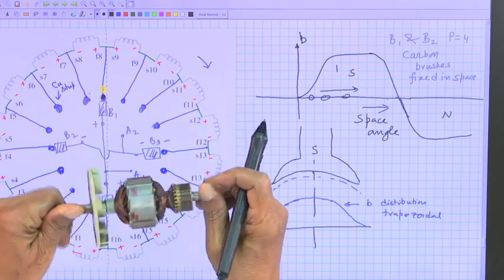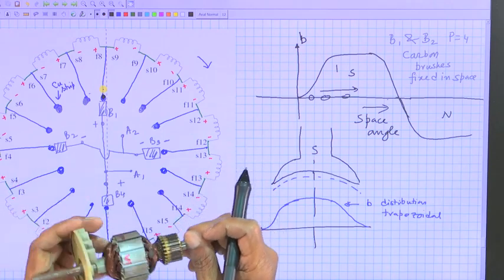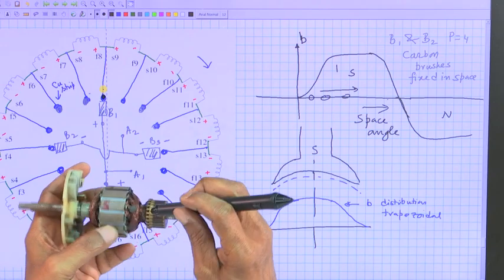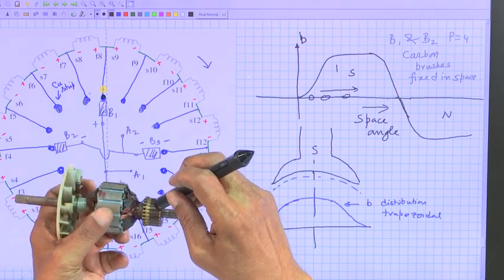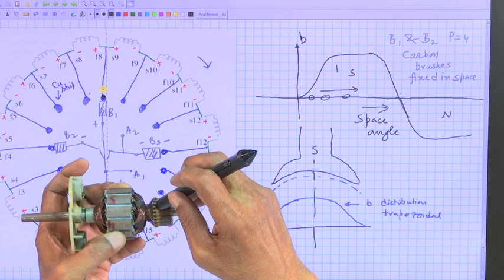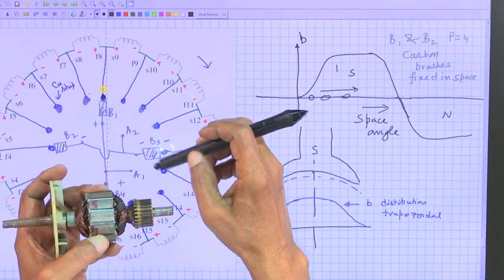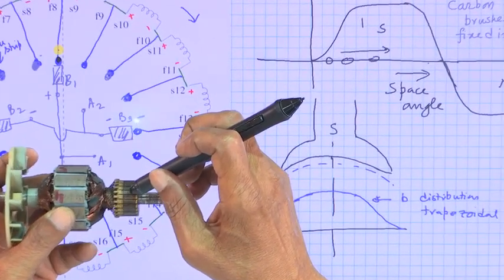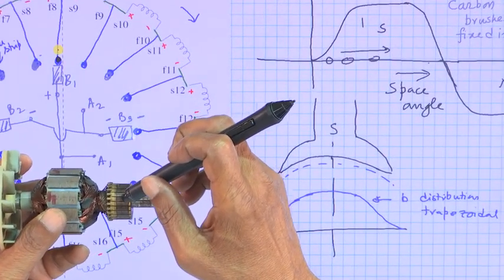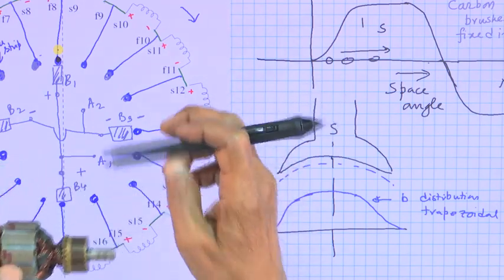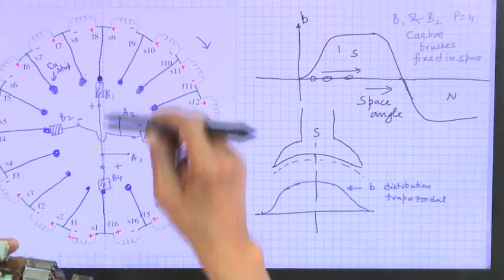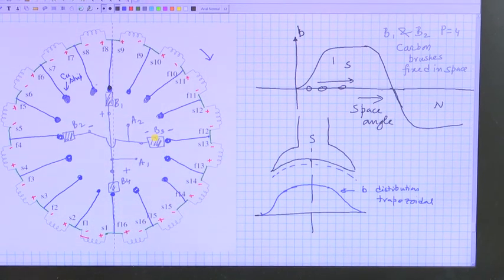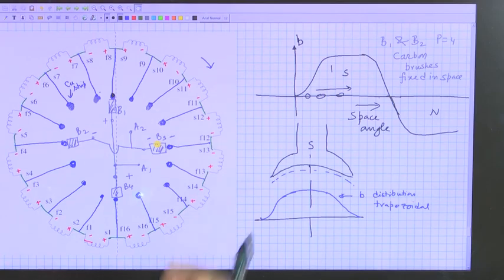So, this whole thing will rotate. Okay. And then we will have carbon brushes. Suppose this tip is a carbon brush placed in space like this and fixed. Therefore, as it rotates, this brush does not rotate, and it will touch whichever coil comes in that position, connecting that particular commutator segment, ensuring that B1 and B4 will always remain positive, B3 and B2 will always remain negative in polarity of the voltage, thereby giving you a DC voltage.